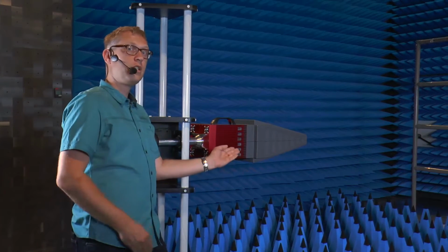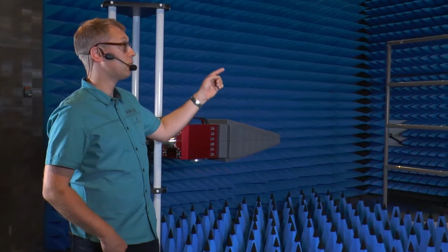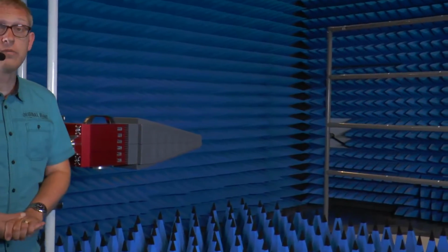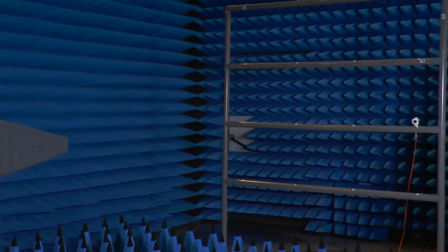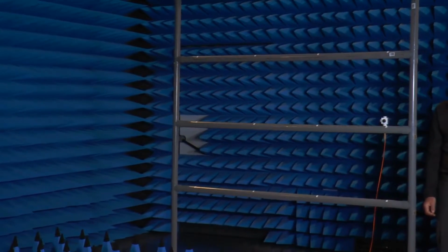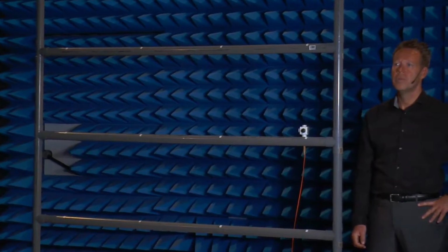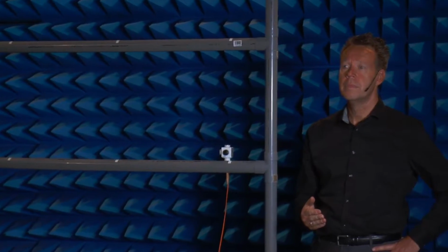Okay, clear. But can you show me what's inside the anechoic chamber? Yes, I can show you how the setup is done inside the anechoic chamber. Here you see the RadiField Tripple A field generator. It's positioned at 3 meters distance from the RadiSense field probe, which is in the calibration jig. The calibration jig is 1.5 by 1.5 meter and exactly specifies the 16 positions that should be measured. These 16 positions are exactly as described in the IEC 61000-4-3. Okay, John, that's clear. But can you show me how the instruments are being controlled from RadiMation? Yes, but then we have to go outside.